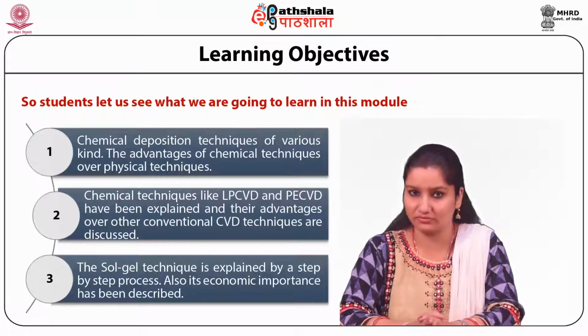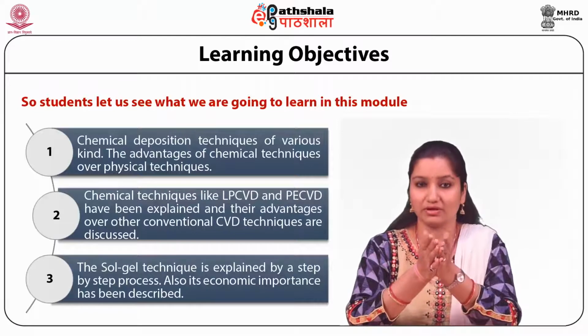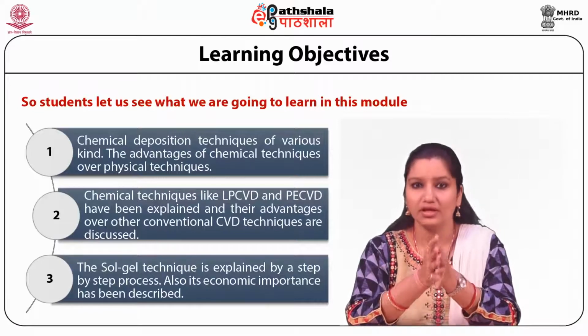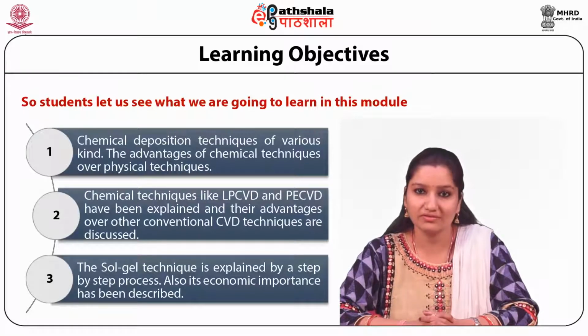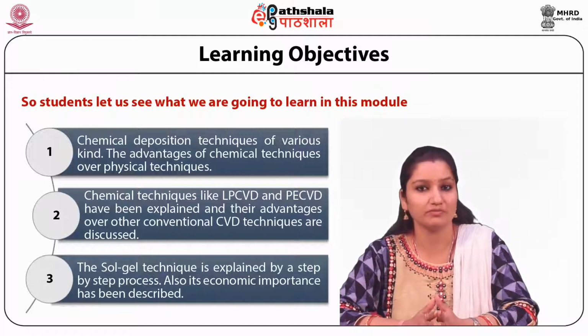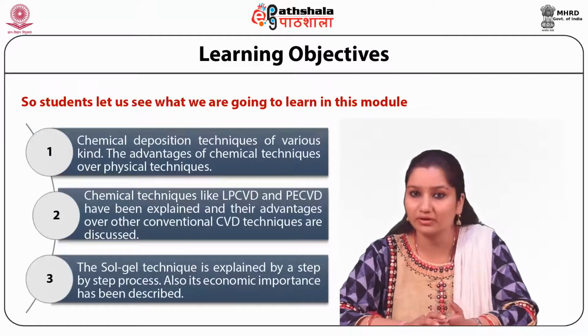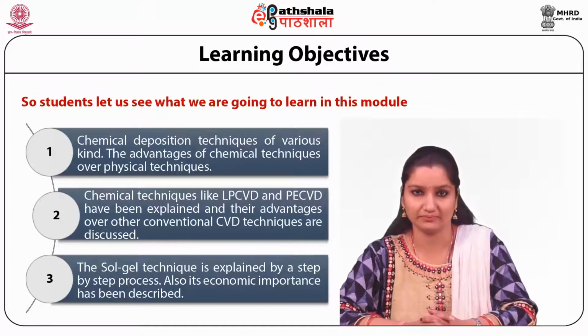Chemical solution deposition process or the CSD technique, or we can call it sol gel processing, is a convenient and versatile method to synthesize ceramics, glass materials in a wide variety of forms such as powders, thin film coatings, microporous inorganic membranes, fibers, monoliths, and porous aerogel materials.